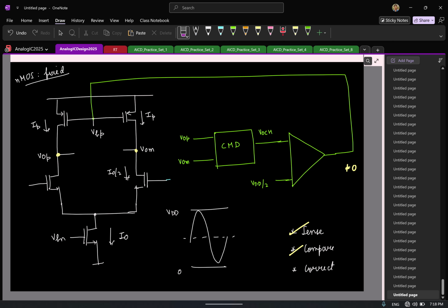So what is missing for the opamp here? Yeah, signs. How do you find what the correct signs are? I mean, this should be in what kind of feedback? So how do you check if it is a negative feedback or not? Break the loop. Let me first draw the full circuit so that you know the loop is formed. So this is VOP. This is VOP. So I can break the loop. Where do you suggest we can break the loop now? Okay, I can break it here.